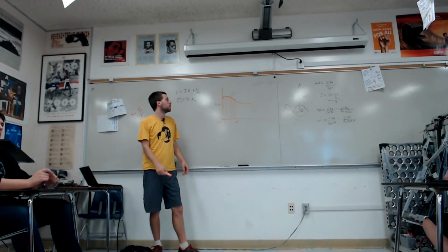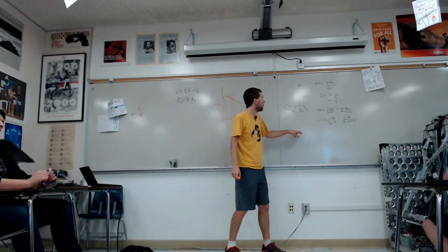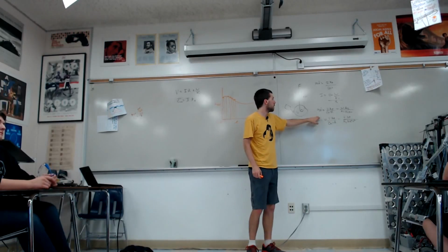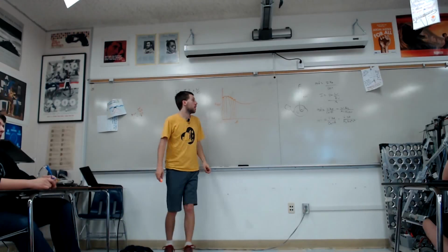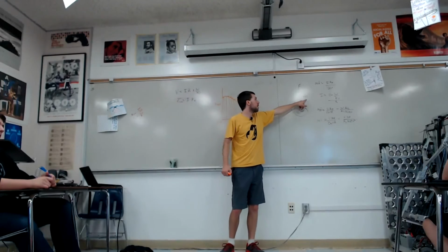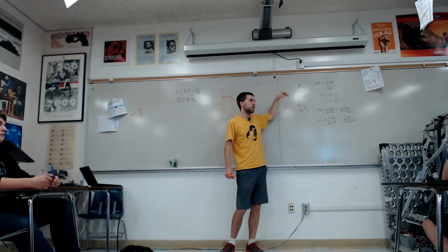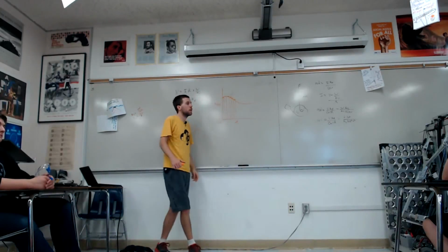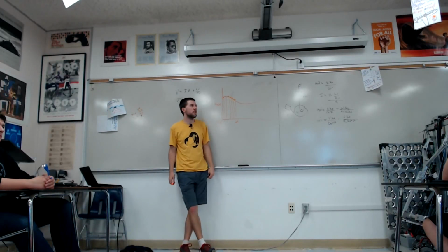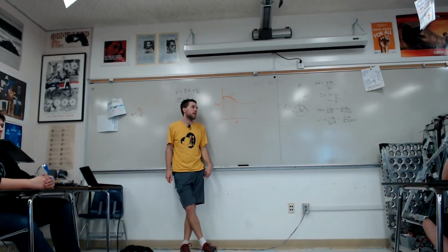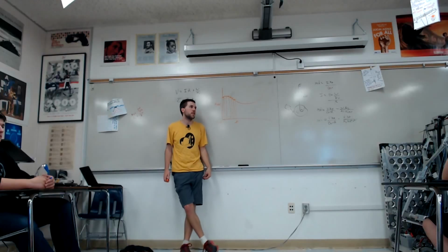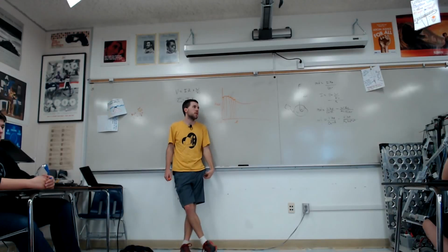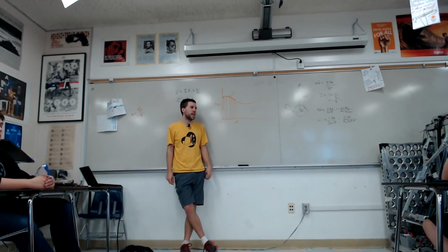Yes? So in the x double dot, are you taking into account gravity here, or is this like...? We can take that into account if we wanted, where we had F equals ma, the force being only the motor force plus gravity. For the most part, I found you can ignore gravity in a lot of the control stuff we do. You want to come up with the simplest possible model that works. But if you think it might be an effect, you can go model it and see how it changes things. We tend to make gear ratios such that gravity is, say, 10, 20% of your load, which is where you can start to get away with ignoring it.